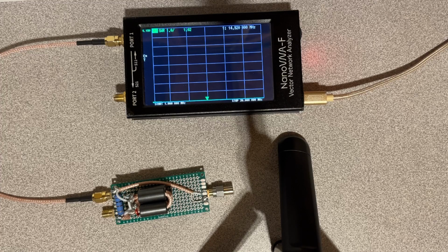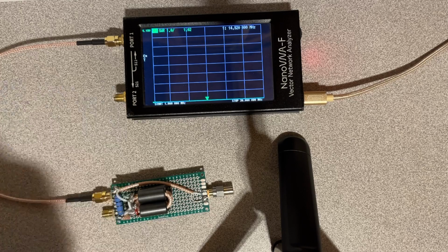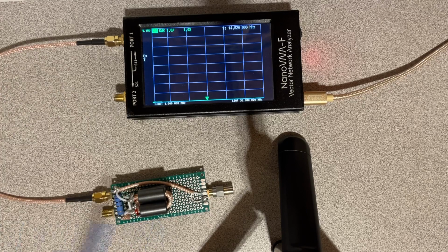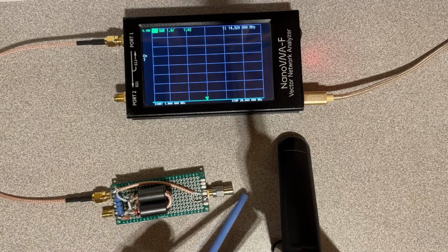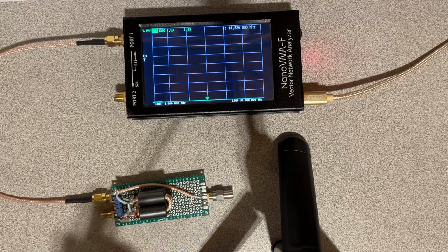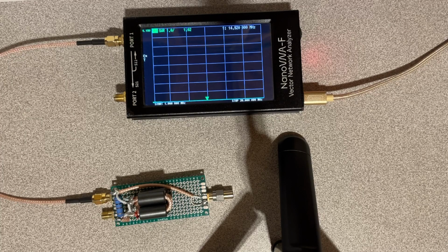Anything 1.2 or less is good performance. So what this tells us is we've got a very good match through the splitter combiner to the 50 ohm load on the output. And when I made the other measurements, I had some of the inputs terminated with 50 ohms and some of the inputs open. So I would follow that. If you're doing your own testing, you should be able to get similar results.